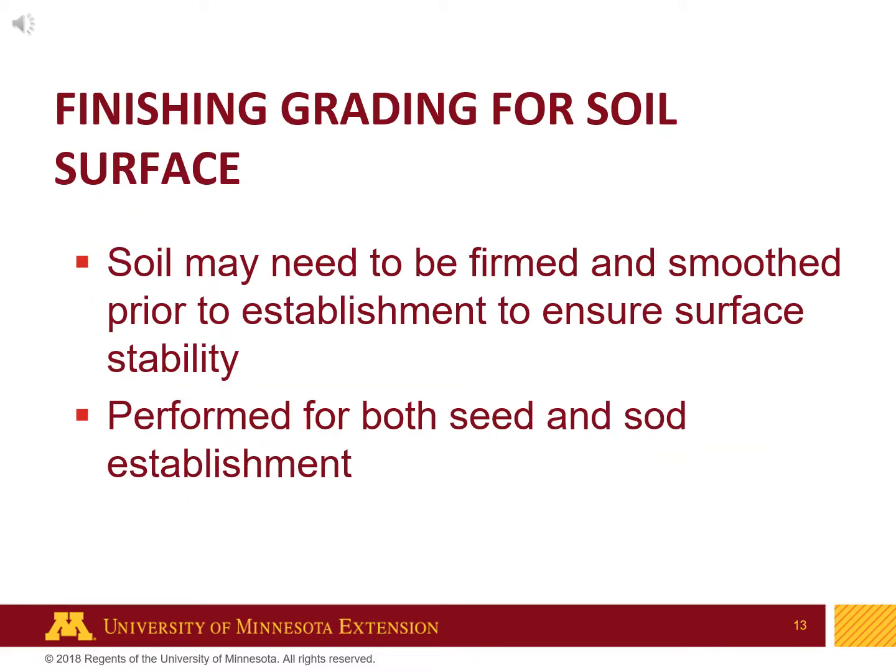After cultivation, a finishing grading for the soil surface to smooth minor undulations may be necessary. The soil may need to be firmed using a roller prior to establishment to ensure surface stability. This final step will be consistent regardless if the site is to be seeded or sodded.